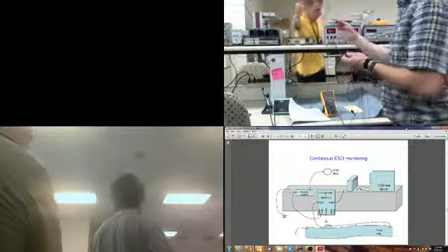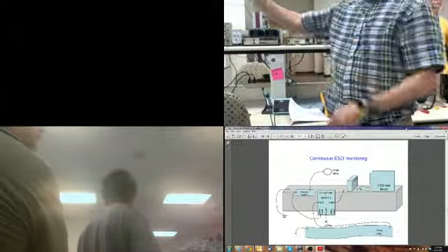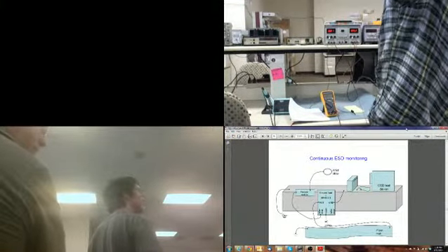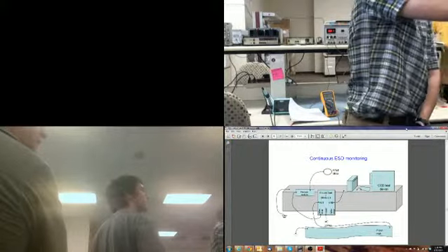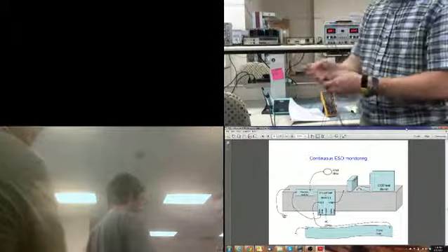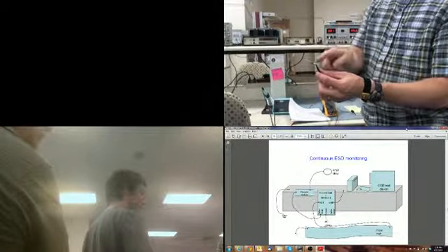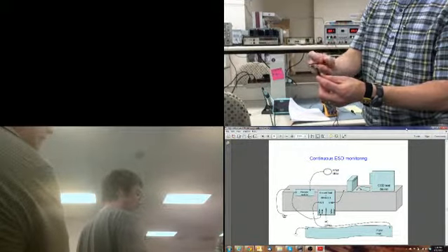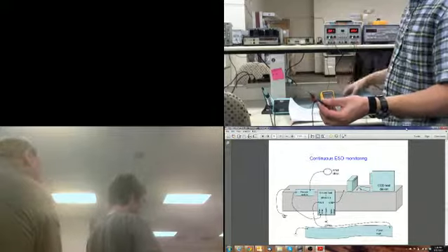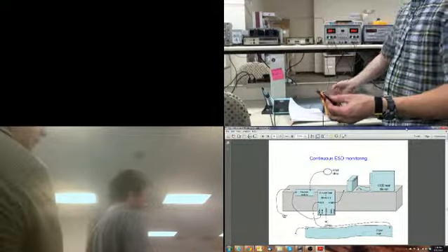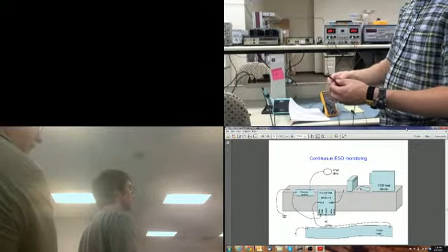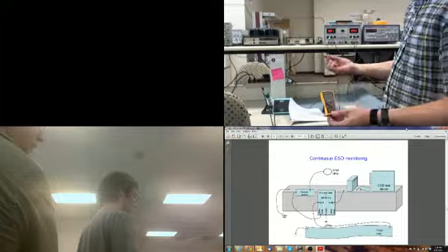Oh, here's one. See the white line on there? That's indicating negative. So you put the meter with the black side on the negative line, the slash line, and then it'll measure, say this is 0.497. The bigger the diode, the lower that number is going to be. If it's a small diode, it'll be about 0.7. So the larger, the less drop you have. And you can measure LEDs and things like that.